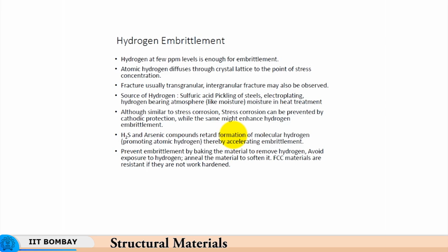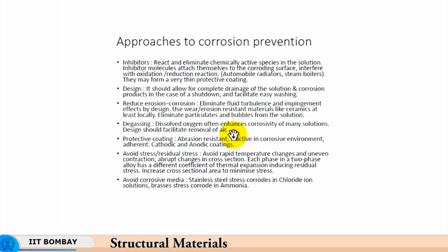Sufficient vacuum should be present so that there is no moisture even in vacuum annealing or vacuum based heat treatment. While we pickle the materials, again hydrogen has a chance to get in. So, pickling has to be followed up with treatments which will get rid of the hydrogen, right.